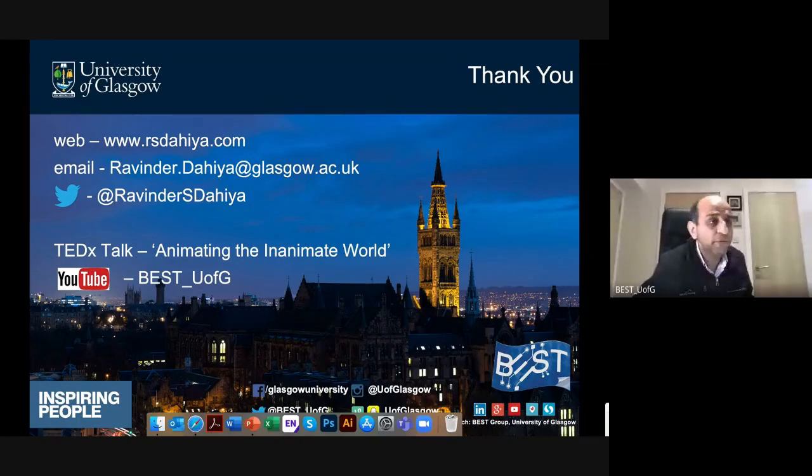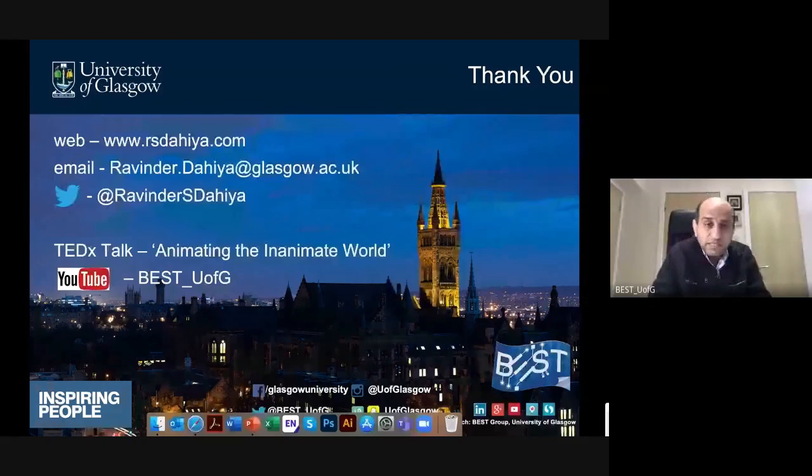What is the typical density of sensors? That depends on the application. The tactile acuity in the fingertip is about 1 millimeter, which means that if you press 2 points closer than 1 millimeter on your fingertip, you will sense them as 1 point. So that defines basically the density of the sensor, 1 millimeter apart.